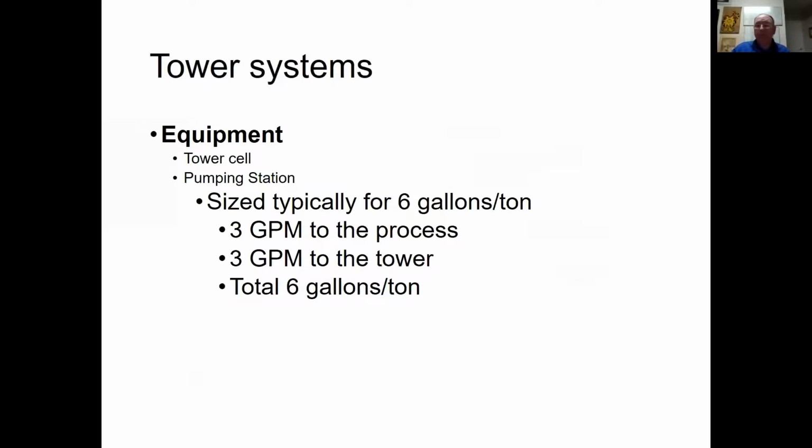Tower system consists of a tower cell, which is outdoors. The tower cell has a fan. It draws air across the wet deck. Water is falling through that wet deck, if you will, and that is where the heat exchange takes place.